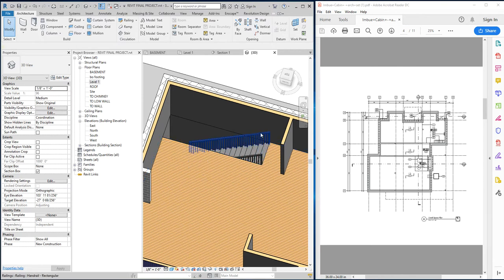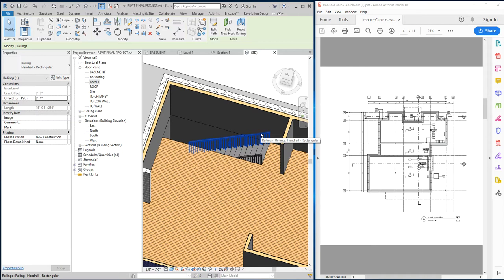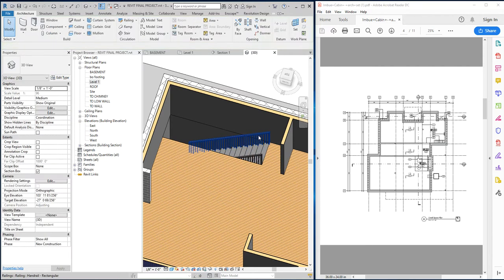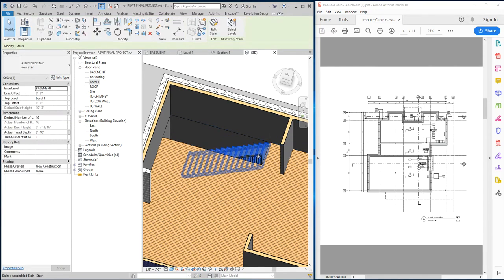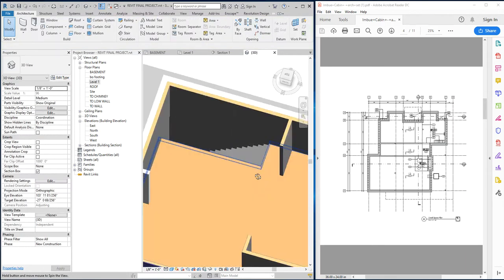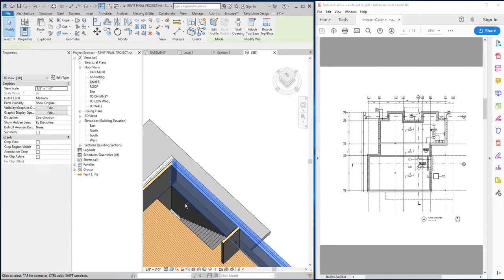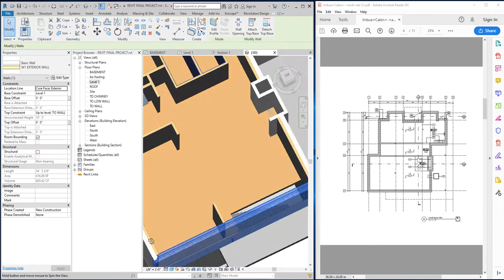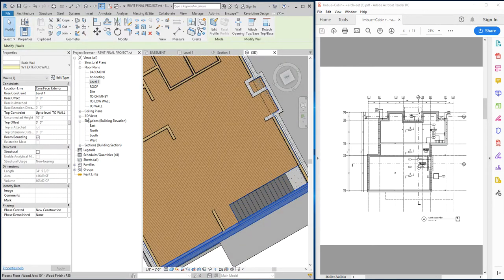All right. The railings are a component of the stair, but they're separate. So we can delete them separate from the stair and not worry about the stair being altered. Okay. So I can click, delete, click, delete, and everything looks good. There they still are. All right. And I'm going to add a railing that is separate from my stair. I'm going to go to my main level.